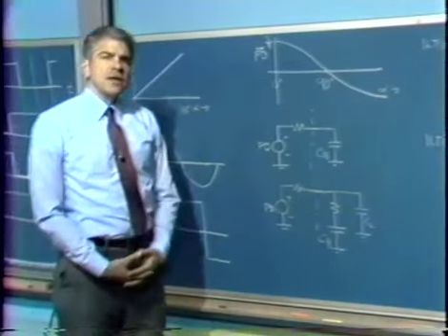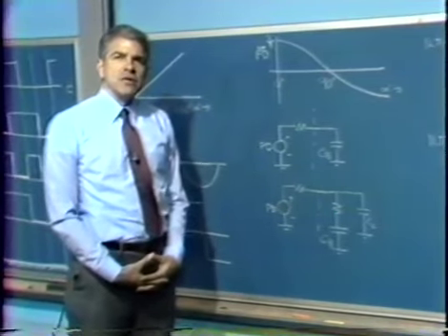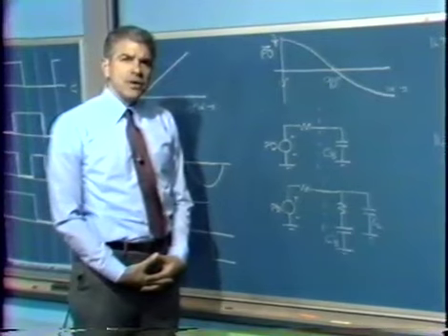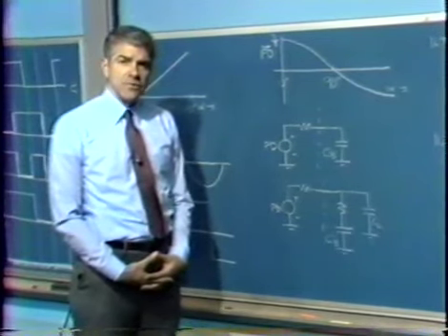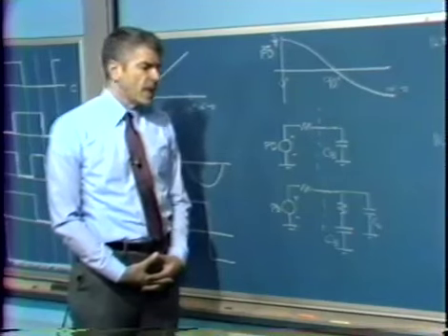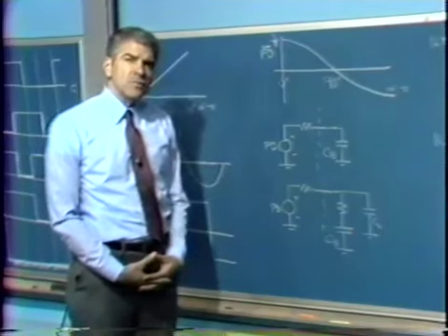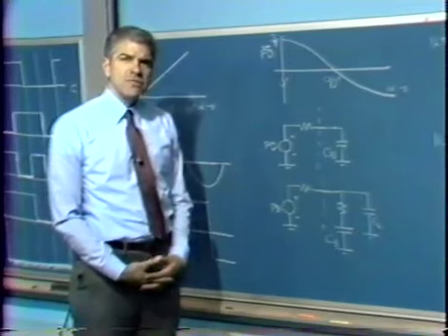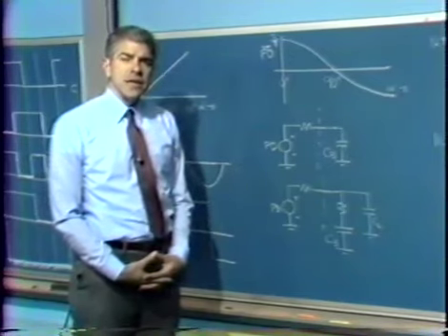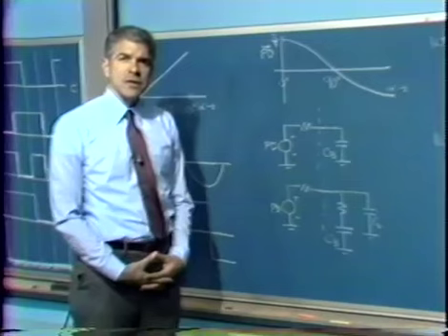In many phase lock loops, we intentionally include an additional integration in the loop. We indicated there was one inherent integration that has to do with the conversion from frequency to phase. But in many loops, we include an additional integration, and the reason for that is so that under steady state conditions, we get 0 phase error in the system.